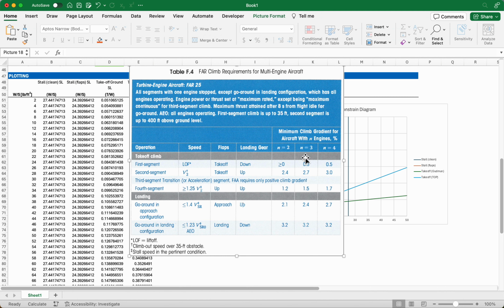engines the aircraft has. So if the aircraft has one engine inoperable, it has to be able to maintain a certain amount of climb capability so that it can do a circle around maneuver and be able to land again safely. So if the aircraft is taking off and exceeds that V1 speed in the balanced field length, and it were to start braking if an engine goes out, it would run out of runway.